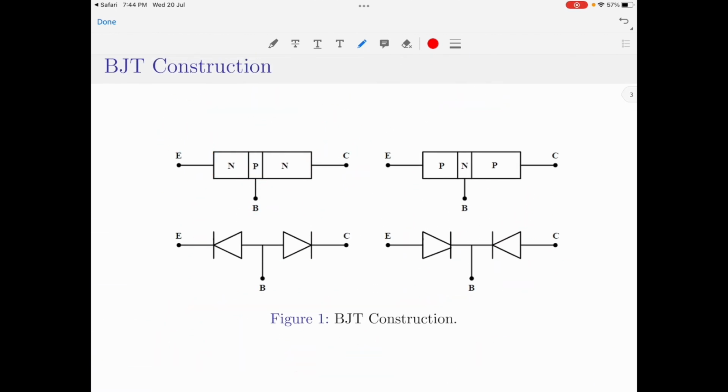Let me first consider a simple PN junction diode, as can be seen drawn at the bottom of the page. For this particular representation, the left terminal is the anode and the right terminal is the cathode. The diode is a unidirectional current carrying device. So, the current direction through this device is always from anode to cathode. So, this is, let us say, ID.